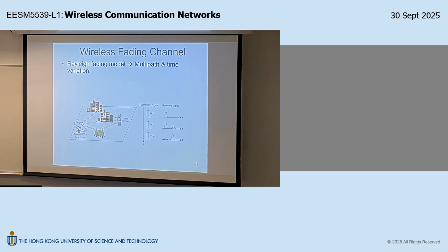By Gauss' law, if you recall from physics, or conservation of energy, the power density that you receive here is given by the total transmission power Pt divided by the surface area of this virtual sphere. If this is a distance of d, what is the surface area? 4 pi d squared, right? That's the 3D surface area of a sphere.